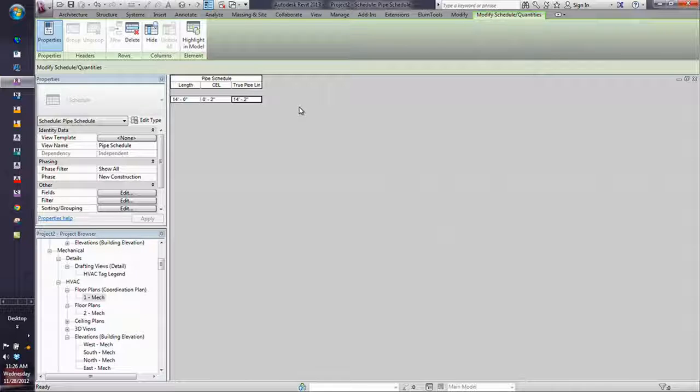Yeah. So we have a wall-based family, or wall-based toilet, right? And then they move the wall as they always do. Now you've got to go and move it, right? Stop. How do you keep a non-hosted family associated with a wall?